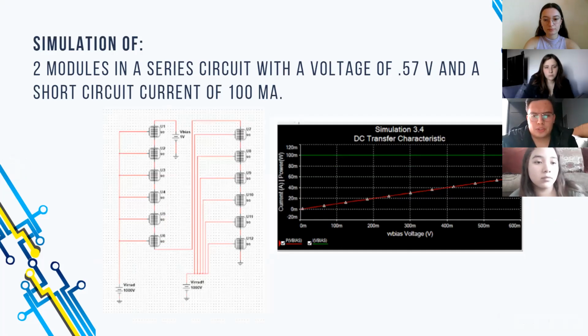Then for the last 2 circuits, we simulated the same 2 models, but this time in a series way. This resulted in a 100 milliampere current, max power output of 57 milliwatts, and also a max power voltage of 0.57 volts. This is the circuit that is in series, and both modules have full sunlight over them.